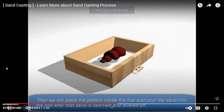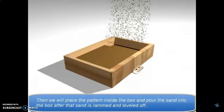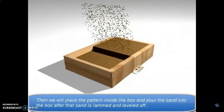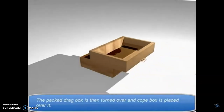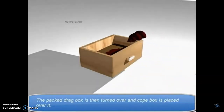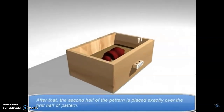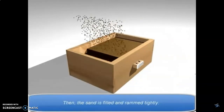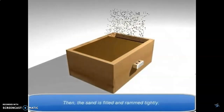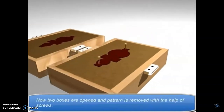As you can see, here we have a box, and that is filled with the sand actually, and in that we have placed one pattern. Okay, and we are ramming the sand, and you can see at the back side we have also a cover that is known as the cope, and the second is exactly the same. You can see this is a symmetric part, which is exactly placed on that part, and again we have filled it with sand, and again we have rammed it tightly, so that no air can be trapped in between.